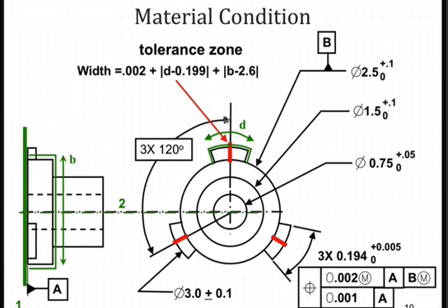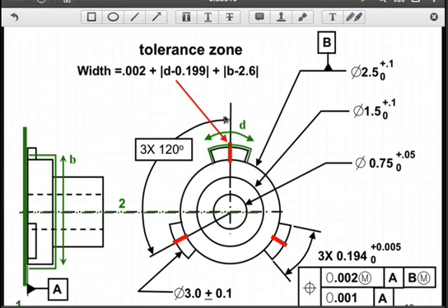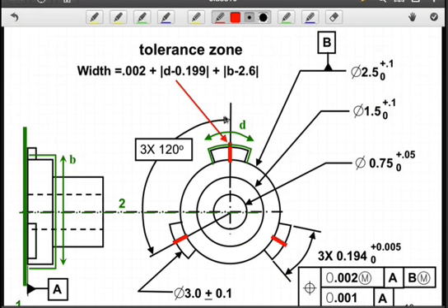Well, you should recognize, first of all, that we have a pattern, and secondly, how are we going to control the location of the features? We need some locating geometry. So in my pattern, I'm looking at 3 tabs, which really means I'm looking at the 2 surfaces. Well, of course, we have to reduce that to 1 locating geometry, and as we've seen before, in this case, we're going to have a plane representing the tab.